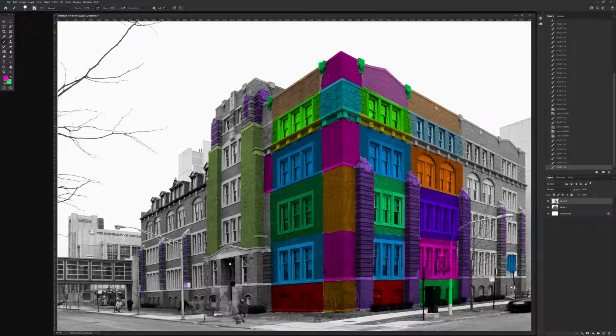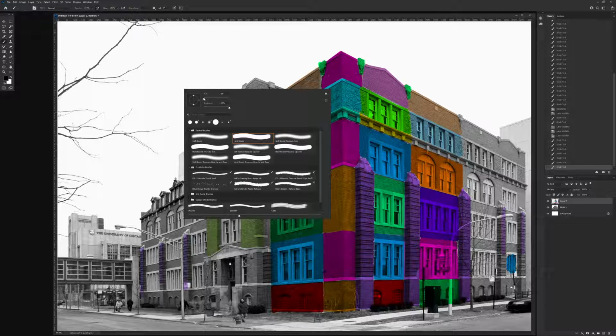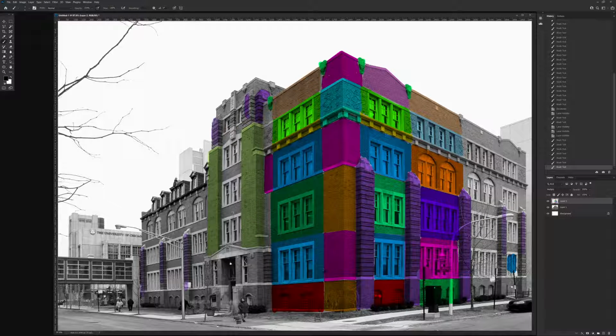And so that means that it's actually going to be a little bit larger than this one, and that's going to be based off the width of this. Now, in terms of the dimensions, I'm going to be using centimeters as a means of identifying the scale of things. So every unit inside of Maya will have a corresponding centimeter unit of measurement, and they will be 1 to 1. So 1 unit inside of Maya will equal 1 centimeter in our game engine.